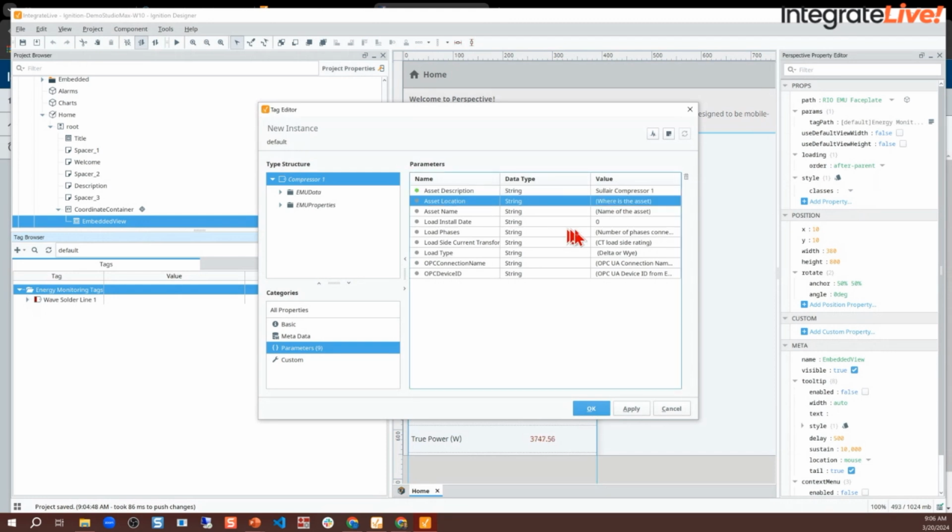As you briefly saw in my earlier session, we've also instrumented our two tool air compressors here at Opto. That's the one where the EMU is a little bit outside the breaker box because the compressors didn't actually have a panel for me to put it into. We've also picked up an analog output, the transducer for the tool air pressure itself, so we can alarm on compressors not running, tool air being low, or anything like that. That's been really helpful.